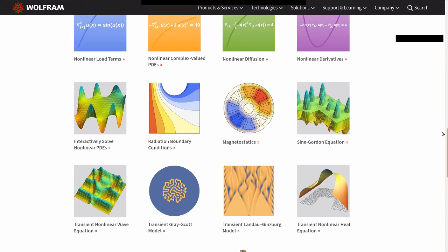That's going to show you how to visualize the mesh. For coarseness and granularity, there are two things you can do. You can specify a parameter, say MaxCellMeasure, that specifies how large the cells are allowed to be, and that's going to give you a certain refinement. Or you can write an entire function that takes out a specific part of a region, for example, and refines that region in that specific area. The keyword to look for there is the mesh refinement function. So both are possible.